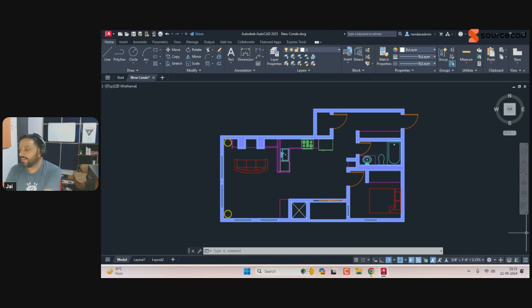Okay, so I have the last question here, how to edit ZWCAD drawing in AutoCAD. Well, you can directly edit the drawings made with ZWCAD. Drawings made with ZWCAD will just show a warning when you open it in AutoCAD that it's not created with the default Autodesk program, but you can ignore it. Okay, and after that, it should work as if it was a simple AutoCAD drawing.